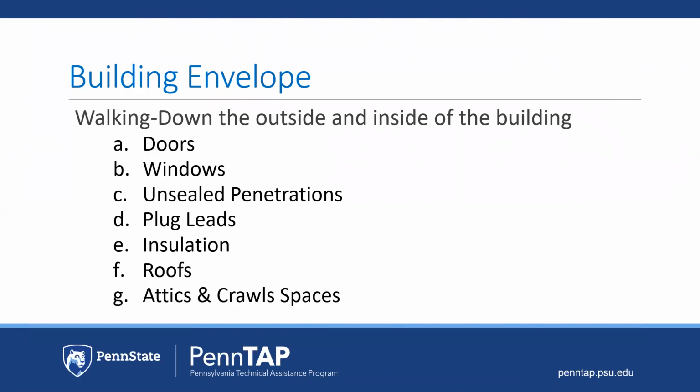Roofs, if you have a white roof, make sure it's clean. Otherwise, you will not be seeing the savings that you originally planned with a white roof. Do you have standing water? If you have standing water, you could have a potential for leaks. This causes a potential for mold and ruined insulation.